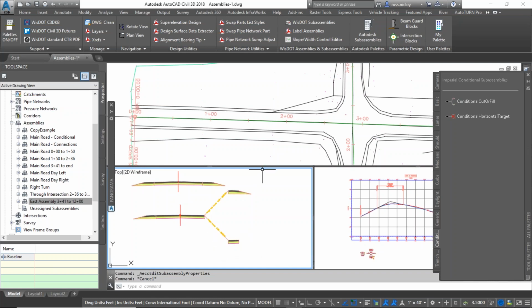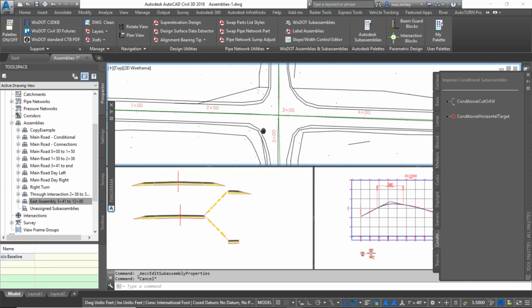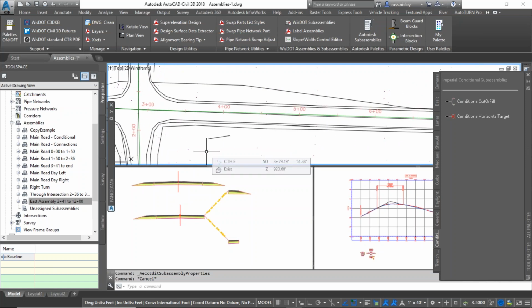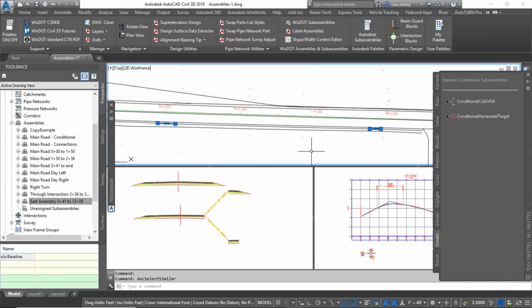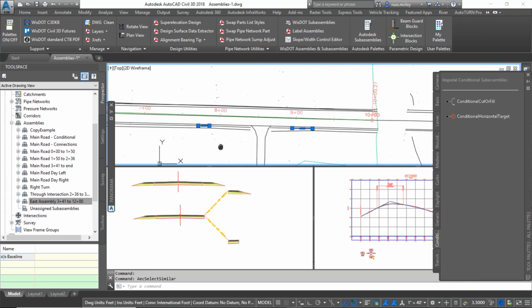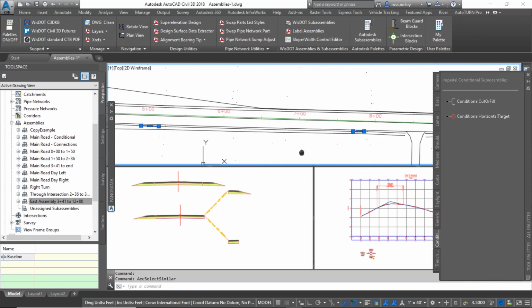What I'm going to do here is go into the, to build a corridor. Actually, I should point out the targets that I'm going to use. I've got some targets in here. One of them I've moved so that you can see it. It's this line right here. That is just a polyline. In fact, if I select it, right click and do select similar, you can see that I actually have some other polylines kind of camouflaged in that the sidewalk endpoint there. Those are my driveway fronts.